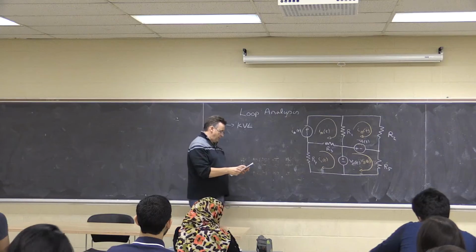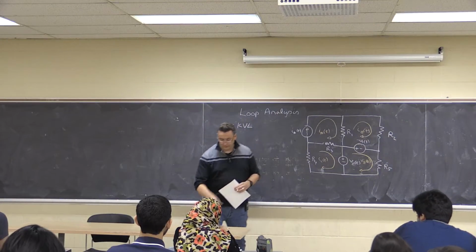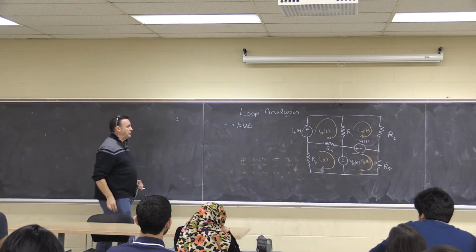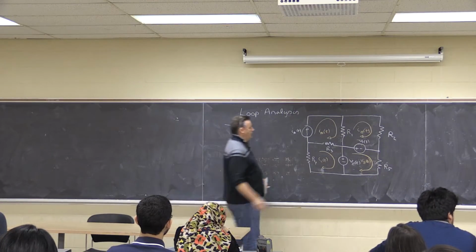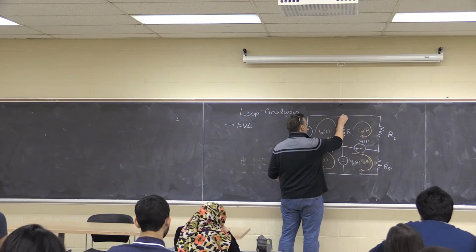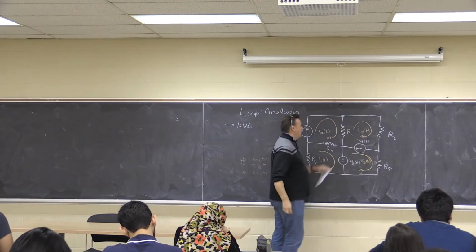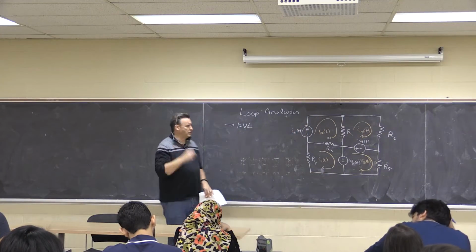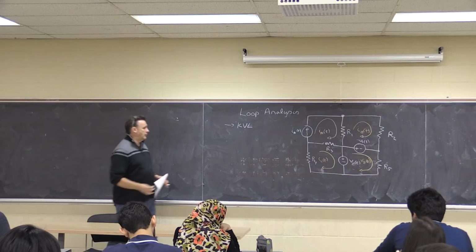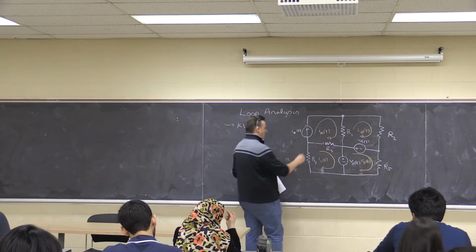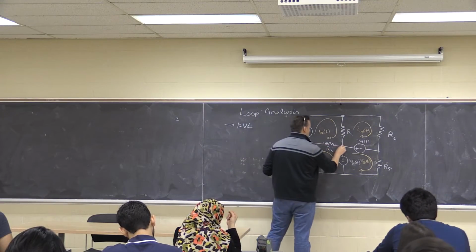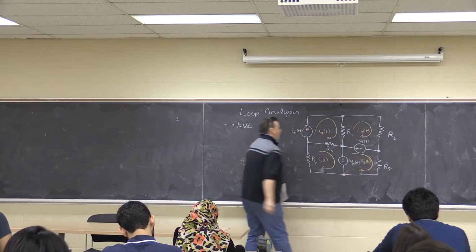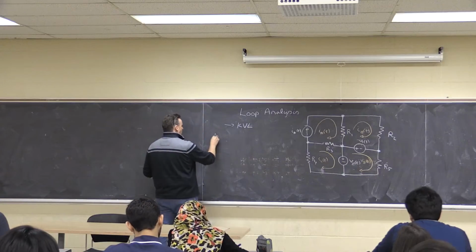If we look a bit further at the circuit, we can look at trying to identify the nodes. Nodes, we'll take in the broadest sense, as when 2 components join together. So we could certainly say there's a node up here, because I've got 1, 2, 3 components. I don't really think this is a node because it's not connecting to another component. So let's just look at the points where multiple components connect together. Certainly a node here, a node here, a node here, a node here. So I could say on this there are 5 nodes.